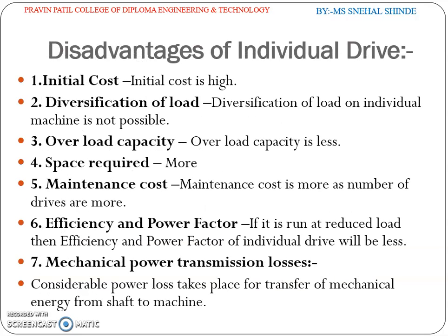Disadvantages of the individual drive. Initial cost is high. Diversification of load on individual machines is not possible. Overload capacity is less. Space required is more. Maintenance cost is more as the number of drives is more.